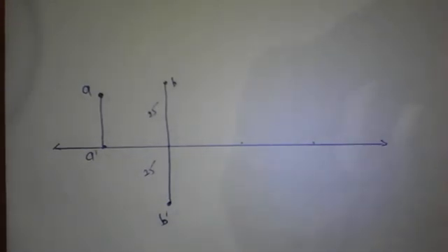Now point C. Point C is 25 mm above HP and 30 mm in front of VP. Above the HP means in the first or second quadrant, and 30 mm in front of VP means it is in the first quadrant, above HP and in front of VP.